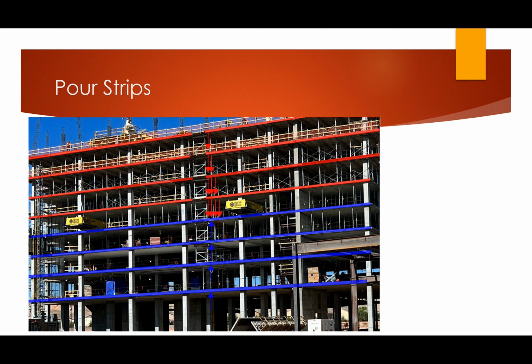Now, if we look at the reshore condition, if you look over here to the left, for example, on this upper level, we have our formwork supporting 100%. And then we have 1, 2, 3 levels of reshoring coming down that dissipate load into the slab. So the contractor actually got the reshoring correct here. What they did not get correct, though, is the backshoring.